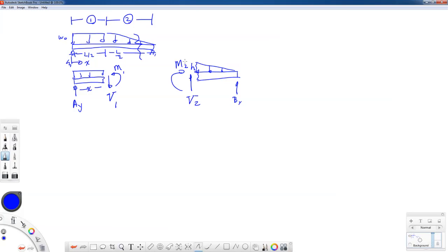Usually that means on the left side. So on this free body diagram, this distance would be L minus x. Okay, don't make another coordinate system. Stick with your original coordinate system. The point is, if your load is discontinuous, we need to make 2 free body diagram cuts to find an M1 of x and a V1 of x, and in this other region, an M2 of x and a V2 of x.